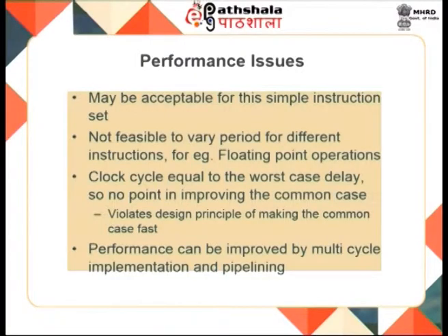This may be acceptable for the simple instruction set that we have considered, but it is obviously not feasible for different instructions which have different types of timing requirements. For example, when you look at complicated instructions like floating point operations, the clock cycle is equal to the worst case delay, and there is no point in improving the common case. So, our fundamental assumption of making common cases fast is going to be beaten here, because you are only going to look at the worst case, and the timing has to be decided based on the worst case. So, this violates the design principle of making the common cases fast.